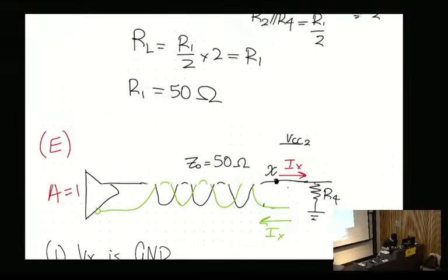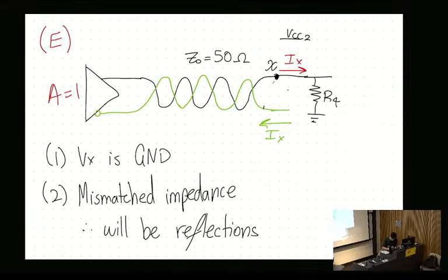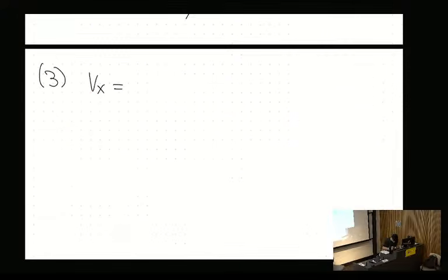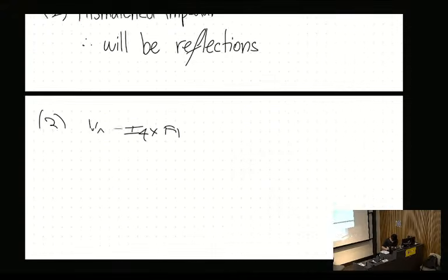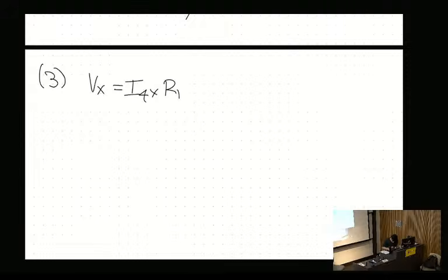So at Vx, the DC offset will just be 0 because we're grounding it. What would the voltage be due to the injection of current? It'll be R4 times Ix, so I4 times R4. Rx should be R1, or R4; I don't know why I wrote Rx. R4 equals 0.5 volts. Okay, then we need to calculate what Vz is.